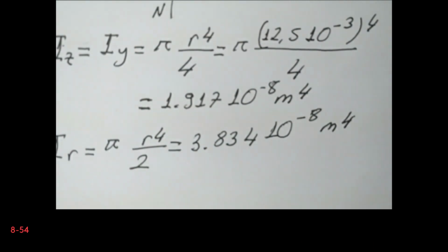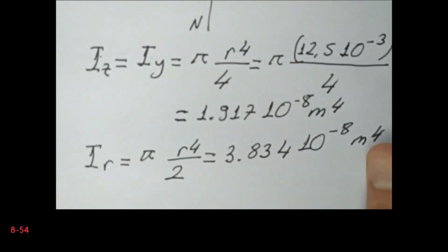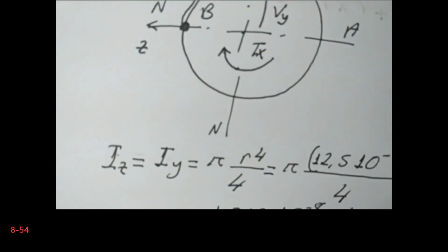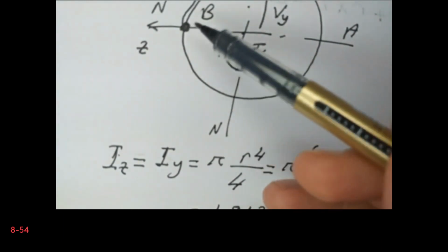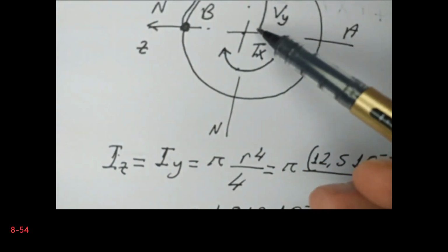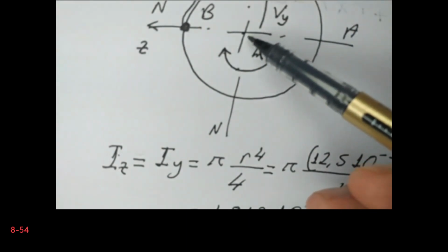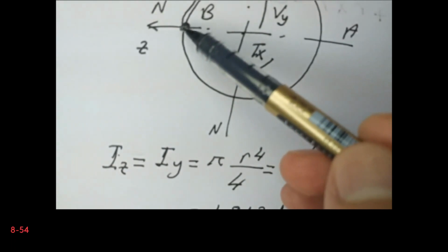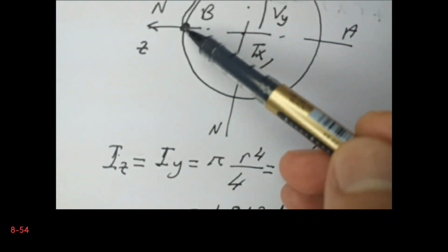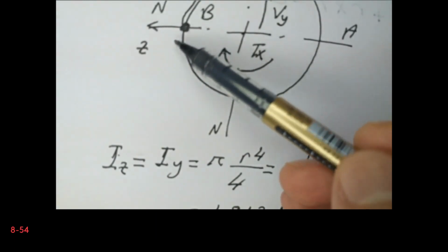Now next we need to calculate the Q value. So we have only, as we said, stress contributed in the y direction, because the stress in z direction will not contribute, because Q is here 0 automatically. In z direction, therefore we will calculate the Q value in y direction.